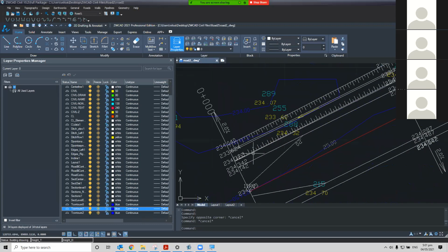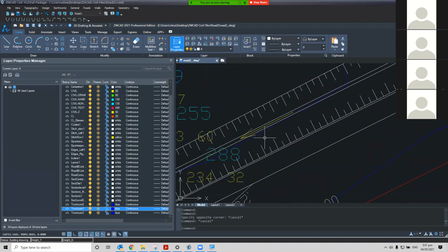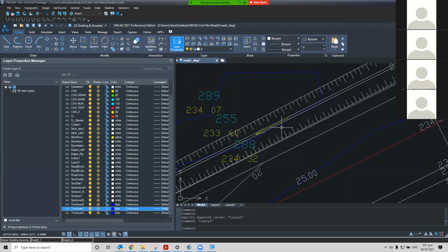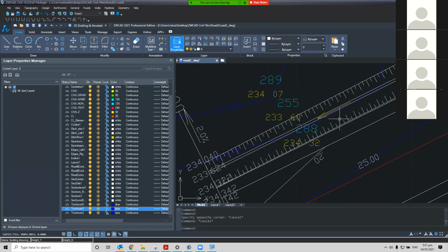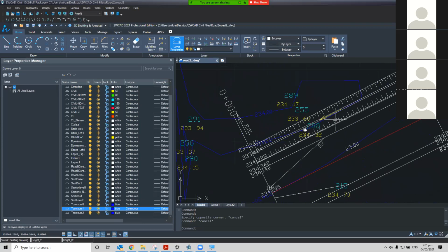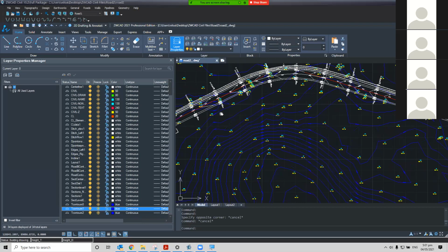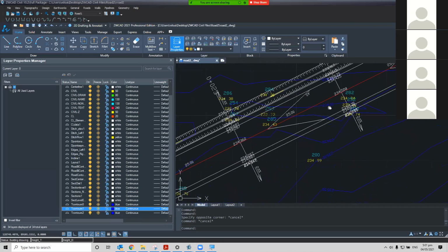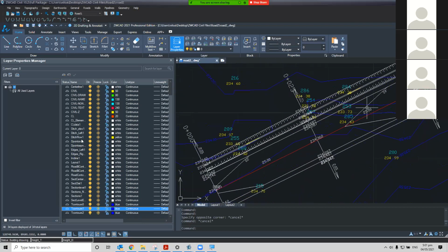Okay. So this is the flow direction, you see? Yep, this one. And the arrow is in the middle of the bottom of your ditch. What you see here is actually the ditch. There's the left slope of the ditch and the right slope of the ditch, and the bottom of the ditch, which was, I think, 0.3. This is what you designed.